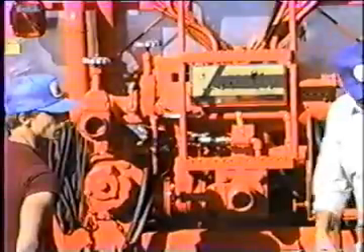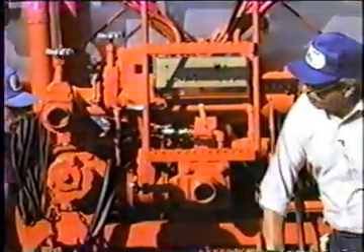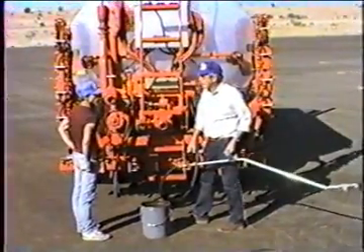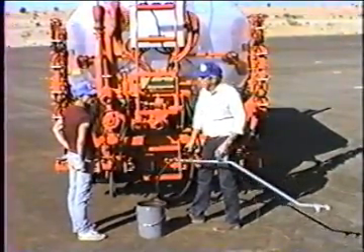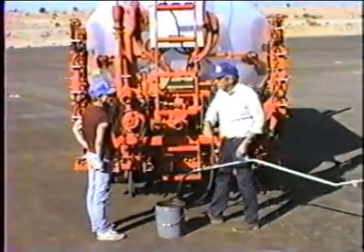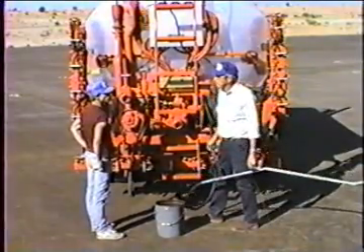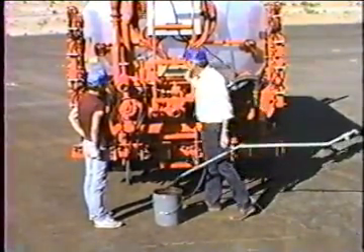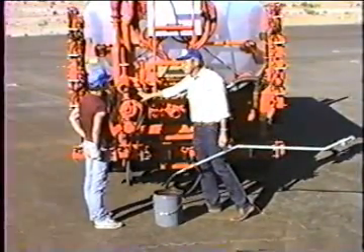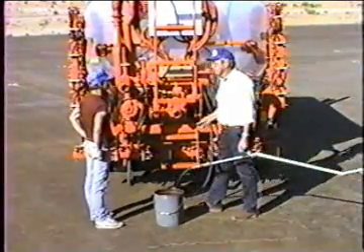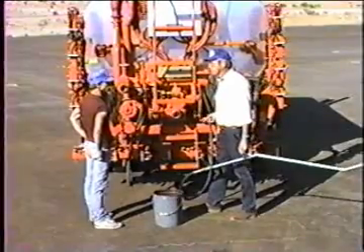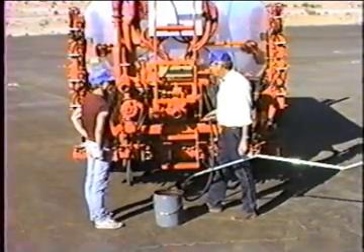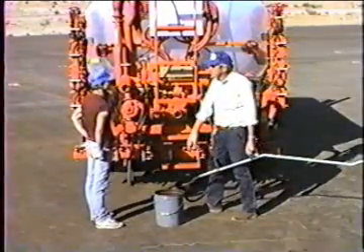Okay, with the handgun valve open, do some more spraying. This works especially good if you're priming, because you can continue to spray a little bit and just let it run until you get diesel, where you recognize that it's down to diesel. Then stop, turn this off, close this valve. Again, you're going to leave the handgun full of diesel. Leave the hose full of diesel. That's the best condition. You can always circulate the next day. That's a little simpler. You don't have to get the bucket out.